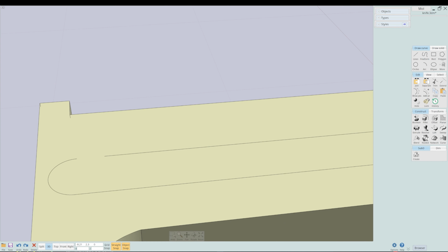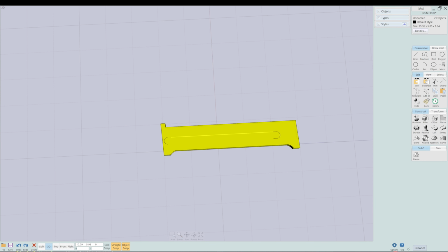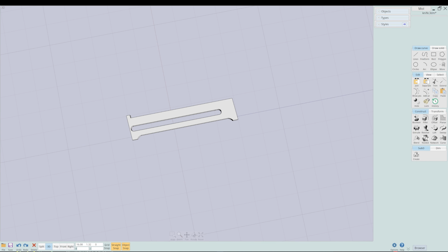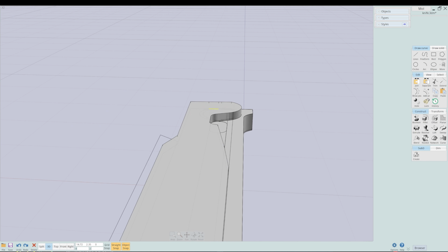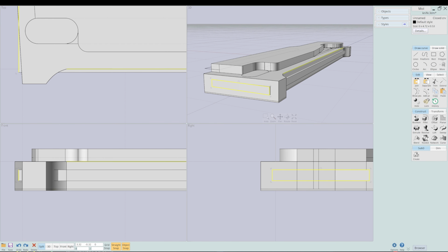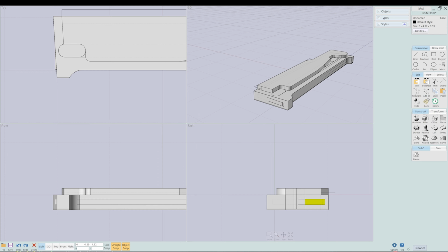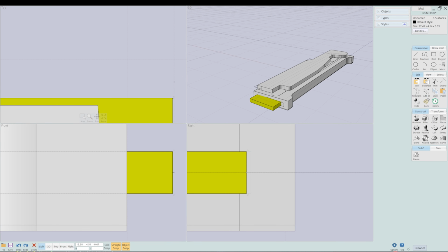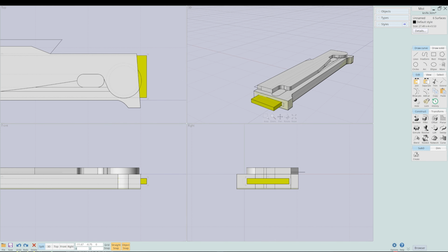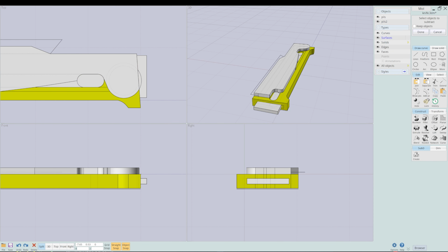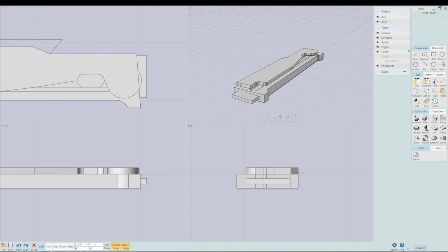A lot of the same stuff. They both can cut lines into other shapes. You cut a line in, you extrude with that line. A lot of times the line will actually cut into two separate parts, which again is another advantage of the CAD softwares, where if I'm splitting up parts in ZBrush, if I want to create two separate parts, it's going to be real tricky. And so a lot of times you'll just drop a panel line or something using DAM standard, or you make indications of these lines, whereas inside of a CAD software, you're actually splitting pieces in half, and if you want to show the line, you can bevel it or use a material difference.